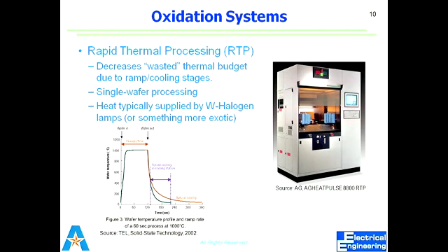Yes, you're right to a certain extent. Thermal budget, or thermal exposure, we say. Thermal budget or thermal exposure is the amount of time for which you put a specific wafer at a certain temperature. So it means that if I have put one wafer